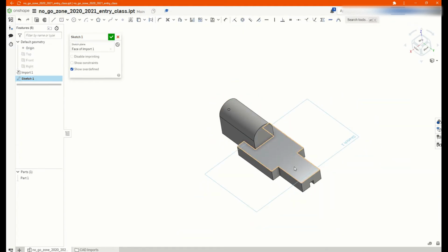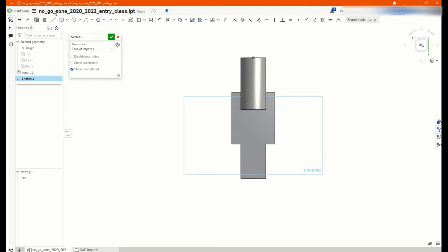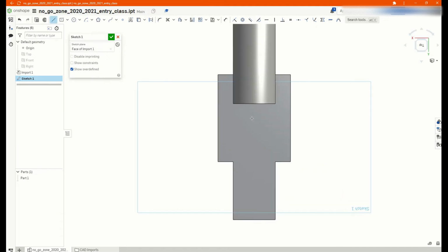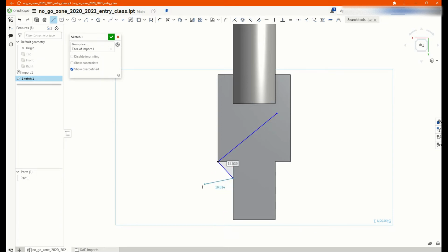You just have to select a plane where you want to sketch, and this allows you to create drawings, which is the base for your 3D modelling. So we have the line tool, which is the basic straight lines, and you can just draw straight lines. You can lock it onto corners, like that. You can also lock it onto lines, and then you can also find the center points, or midpoints. And if you press escape, you can escape the line feature.